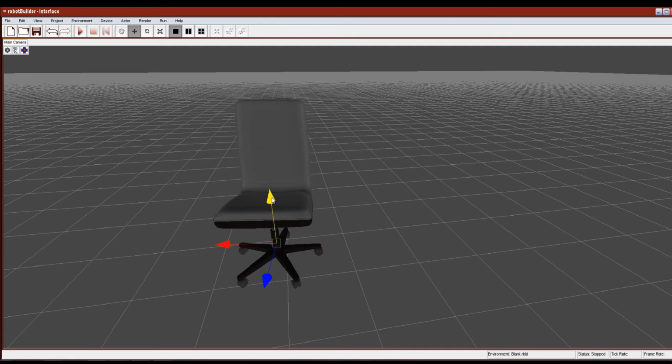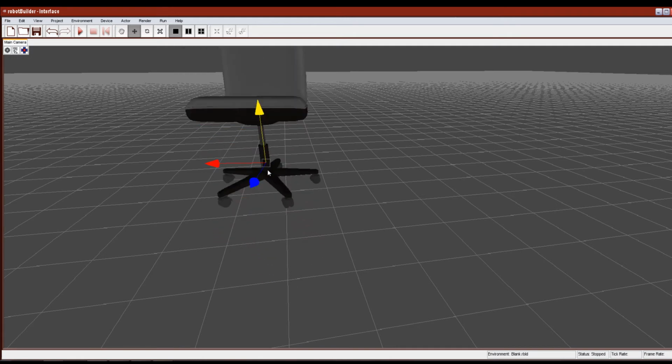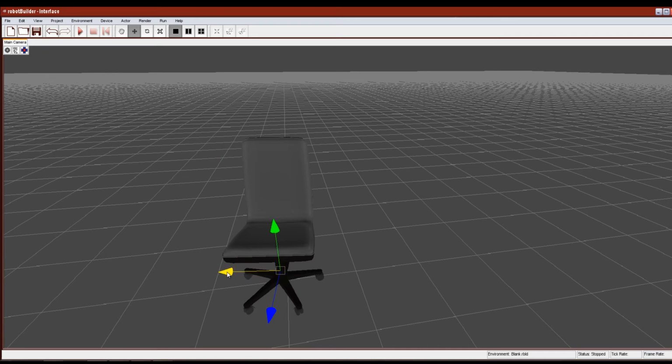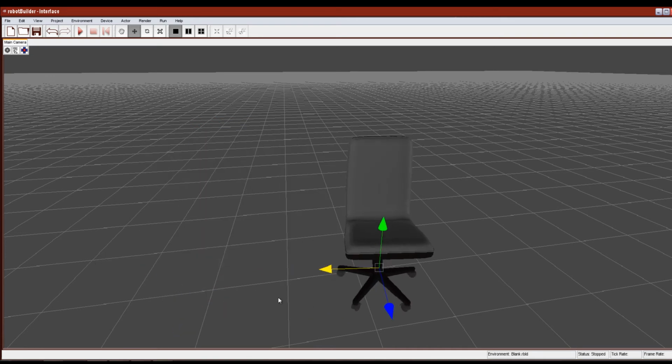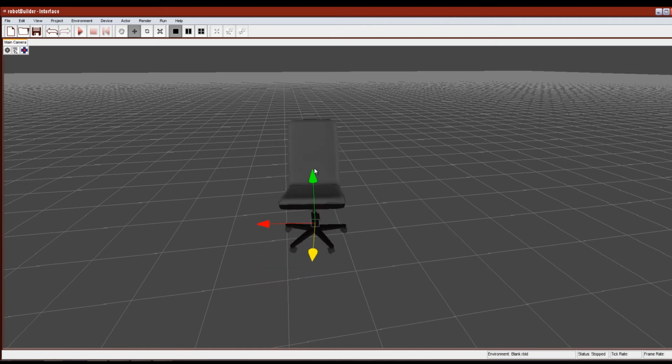And basically once I've picked an axis, I just need to drag my mouse in the desired direction. So here I can move my mouse along Y, can move my mouse along X. I can push this chair, bring it towards me rather, push it away from me. I can click on this rotational tool and it works very much the same way. Selected axis highlights yellow, and now I'm rotating this chair along its y-axis. I can just as well highlight it along the z-axis.